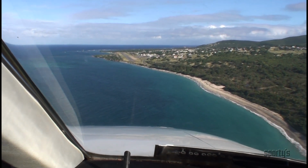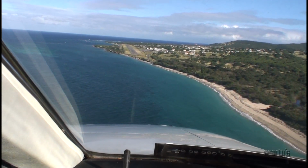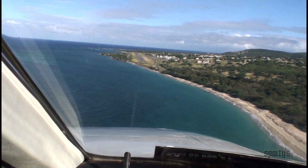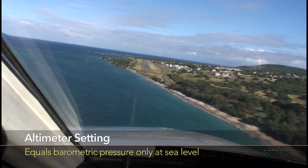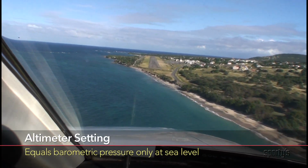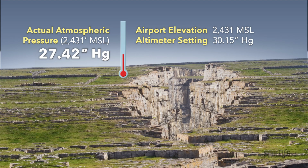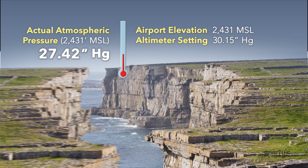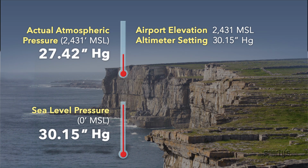All altimeter settings are given on the basis of sea level pressure, providing a common reference for altitude separation of aircraft. The altimeter setting is the same as the barometric pressure only if you are at sea level. For airports at higher elevations, the altimeter setting is what a barometer would read if you could put it in the bottom of a pit dug down to sea level.